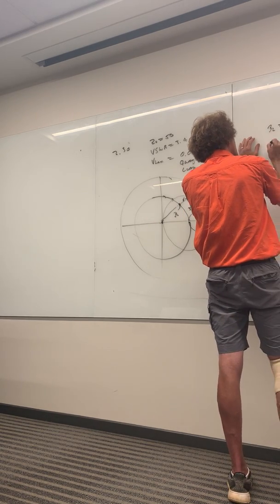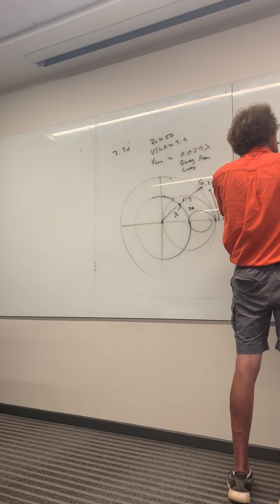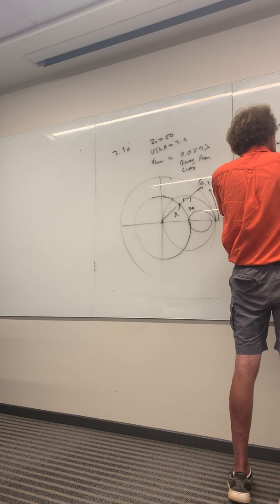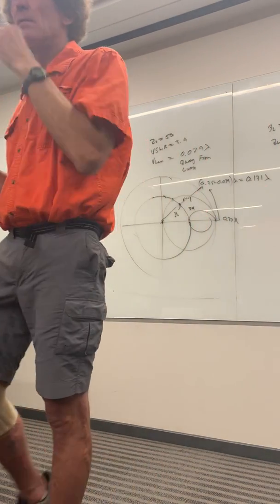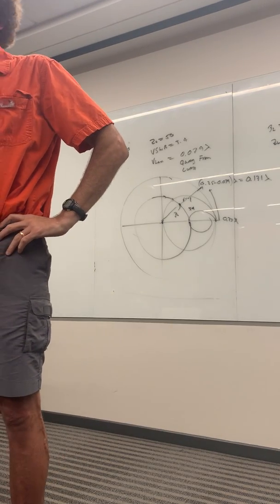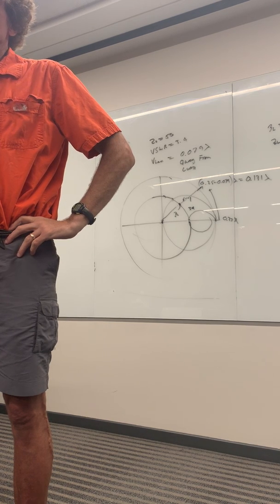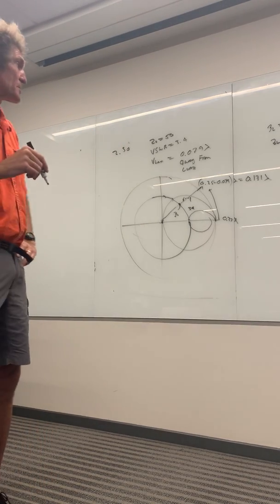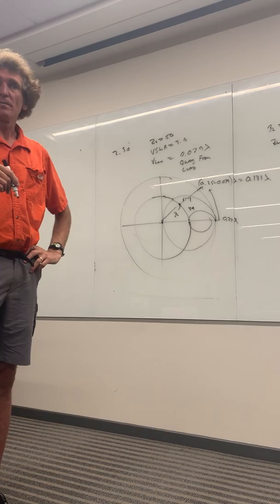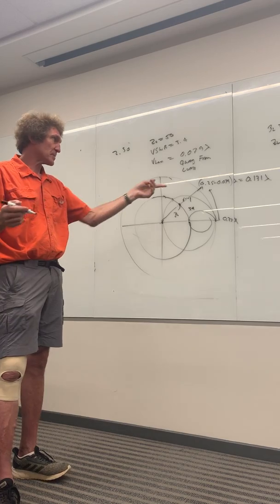That means the actual value of ZL would be Z naught times small ZL, which is going to be 50 plus J what? 65. That's about right, ohms. Is that the answer? No, the answer in the solution was wrong. When you did 0.25 minus 0.079 lambda, the answer wasn't 0.171, it was just 0.071 throughout the solution. They subtracted wrong. That would be way over here. That's what it is in the solution. So it's the wrong answer, but this is how it should be.